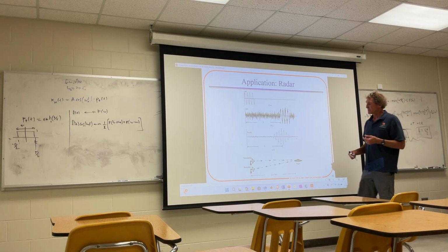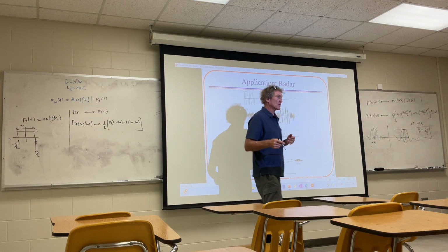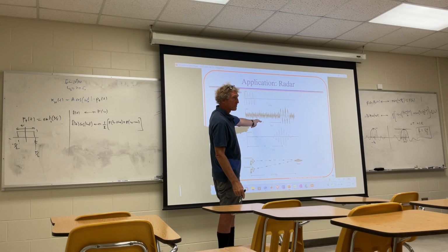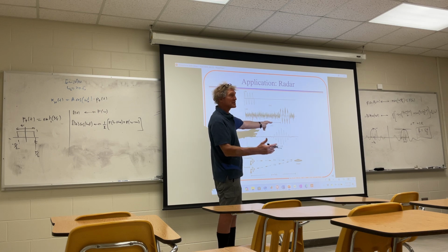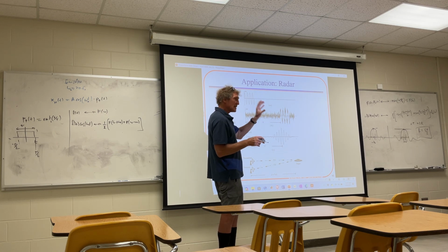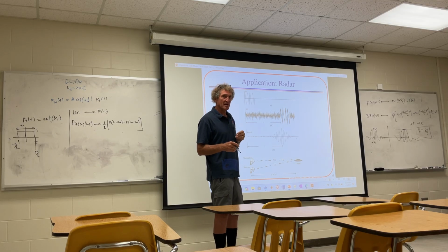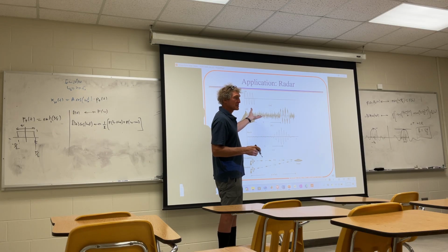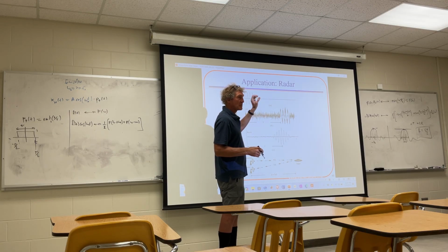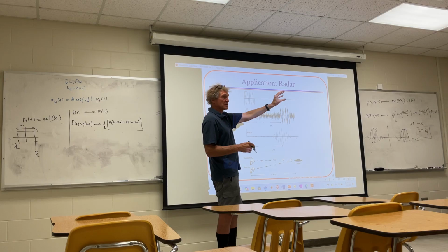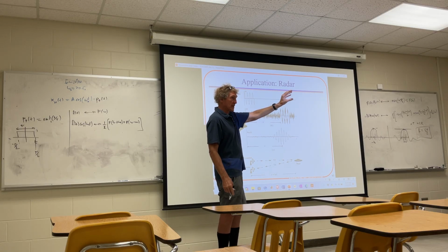Obviously, this is my area, so I'll spend a little more time talking about it, but I want to show you the applications. So if I send this and I listen, I have to be listening at a specific frequency range, by the way, because in the real world, if you just listen for everything in the frequency domain, you're going to get crap that'll just saturate everything. You'll never be able to see anything. So what we're really talking about is something that would be frequency limited, and you'd be looking only at a certain azimuth and elevation in terms of an angle that you're looking at.